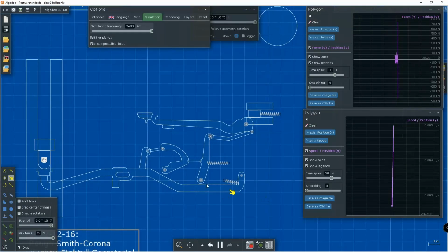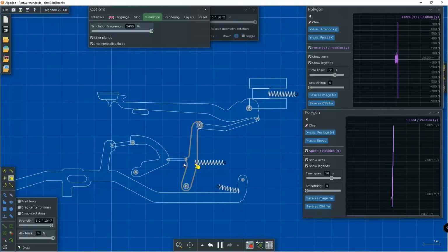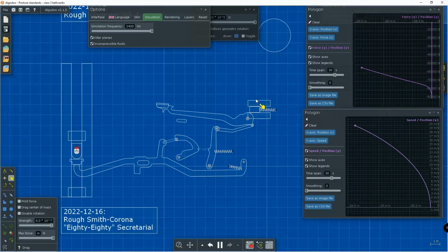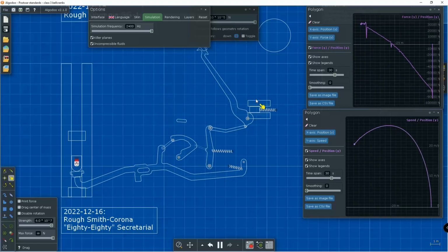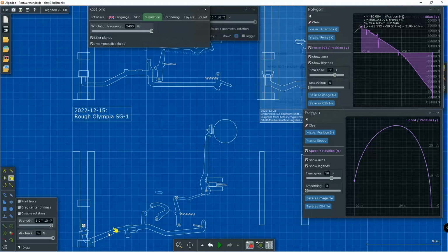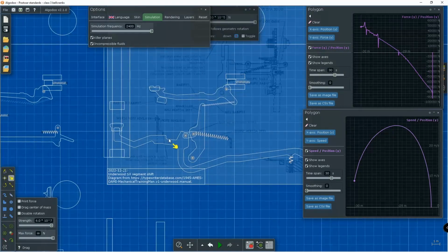So yeah, class 2 lever here. Then if you take this effort arm here, yeah, this would technically be a class 2 Bellcrank. Anyways, that eventually pulls a class 3 Bellcrank for sure. And our force curve will be very similar. And indeed, in real life, I find that these two machines feel quite similar, though this Underwood has a slightly heavier touch.